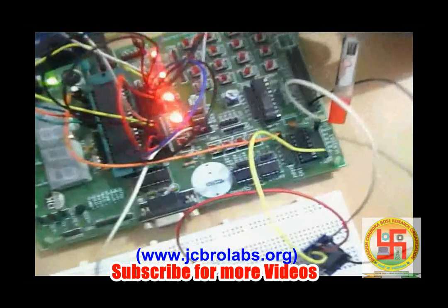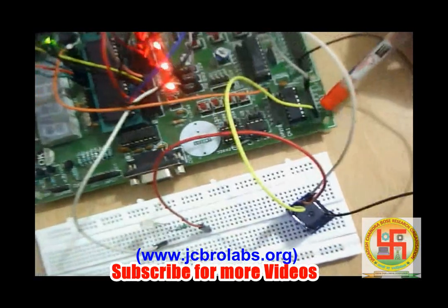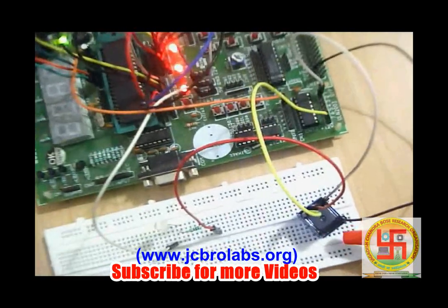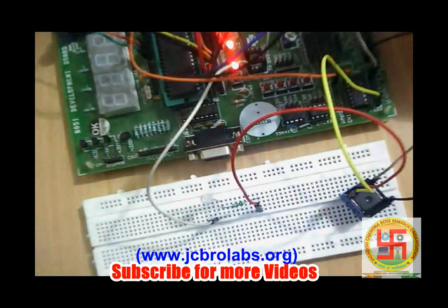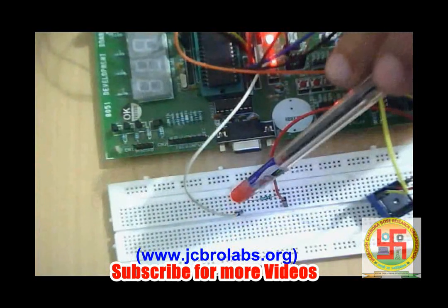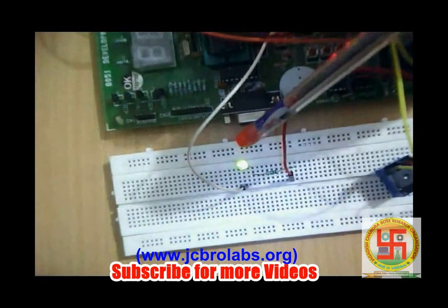Now the output of this ULN2003 is connected to the relay, as we have discussed in the circuit, and 12 volt is connected at one point. Now in order to demonstrate that this relay is working, we have implemented a small LED circuit on this breadboard, and this is the circuit and this is the LED. If you see, okay, this is glowing, so let's change the direction. Yes, so this was the LED.